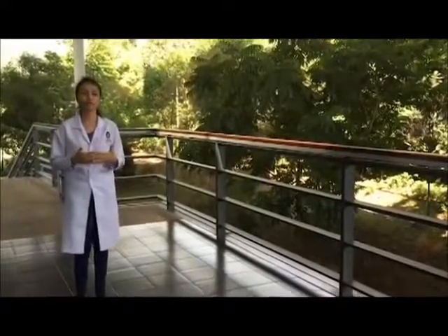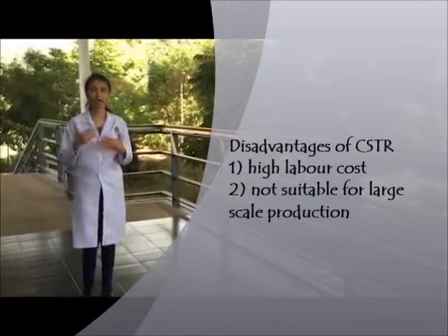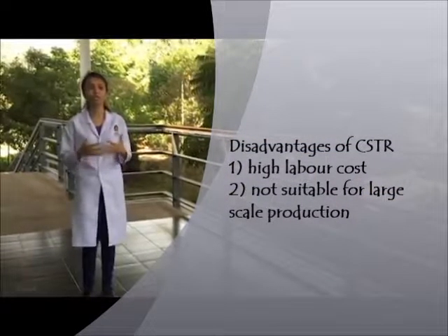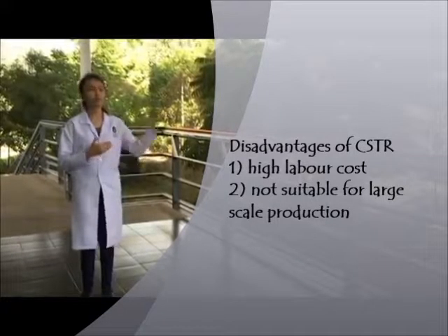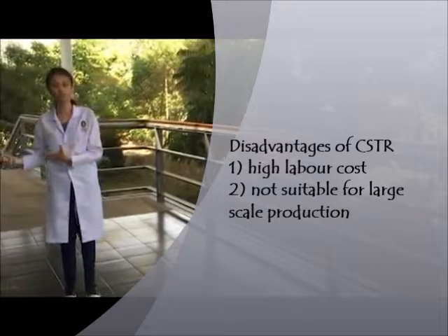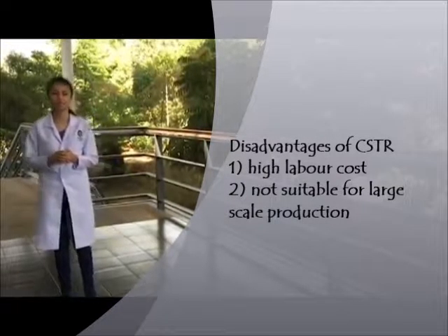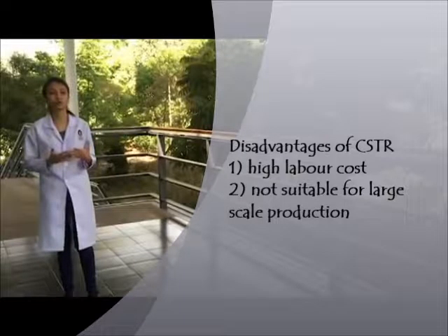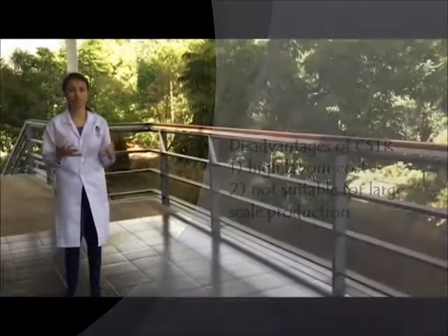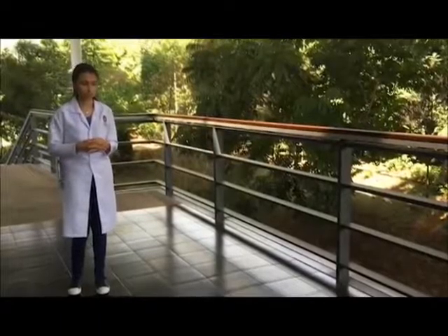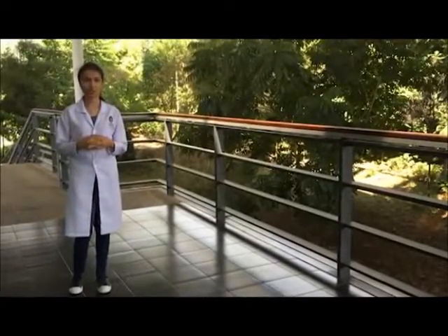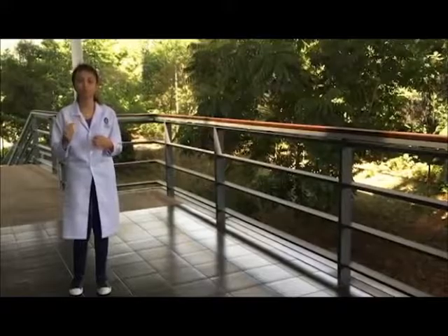And the disadvantages are that it has a high labor cost per unit volume, because you need laborers to manually put in the reactants and also to remove the products at the end. Another disadvantage is that it is not used for large scales of products. So the application in industries is that it is used for small scale production and also for expensive products, such as in the pharmaceutical industry and also the production of dye.